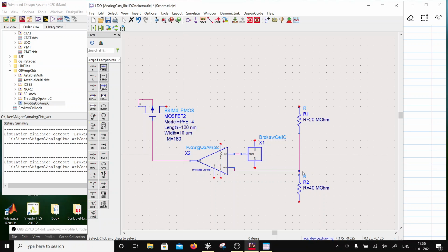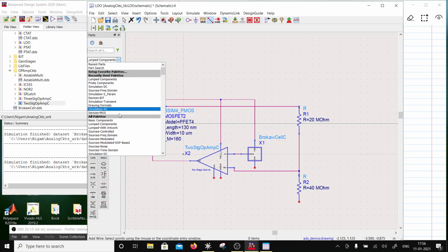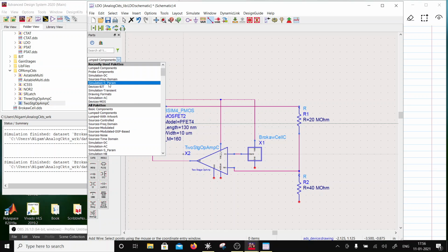Now if you want a still lower limit, you can put a level shifter in here that will control this, so you can still bring down that limit. Or you can put a level shifter here. So you have to shift up the voltage here, or shift down the voltage here. Anyways, this is the output, and this is going to be the bias for this, and this is going to be the ground. So I need 20 microamps of current for the op amp. 20 microamp.